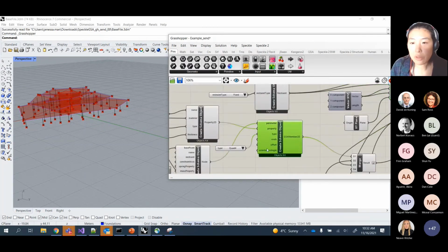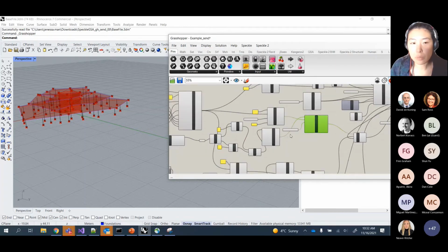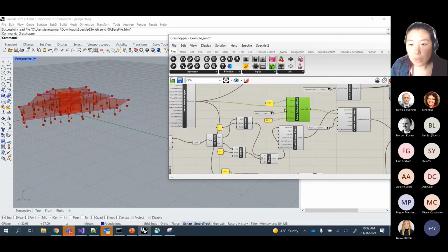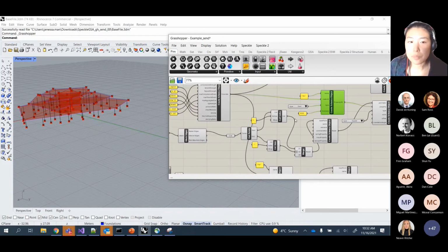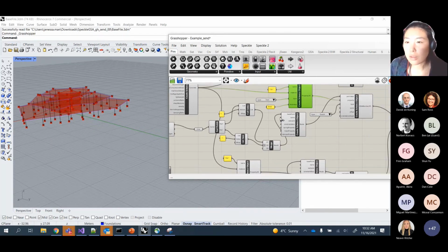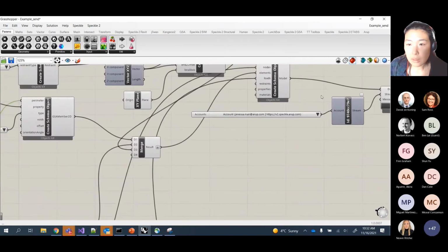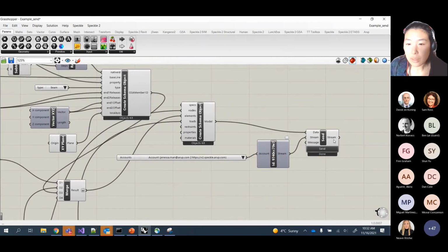In terms of the 2D, very similar story. So we're specifying the geometry based on the perimeter nodes that represent the floor plate. We're attaching some properties as well. In this case, it's a 2D element. We'll do a shell, and we'll do a 300 thickness uniform 2D property. And I'll do this as well again. So we're going to bundle up.